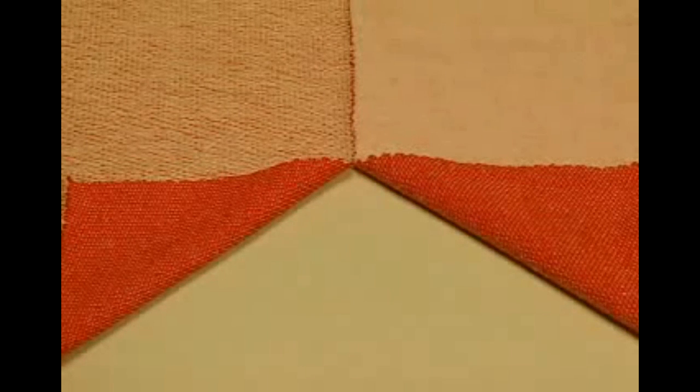This checkerboard pattern uses gray and white yarns. When the gray yarn knits, forming a gray square on the front, the white yarn floats to the back. If you turn the fabric over and inspect the back, the colors appear reversed. A second use is to create surface effects or change the performance of the fabric. You can make loops float on one side of the fabric, then nap them to produce a fleece. If not napped, these floats can be used for aesthetics or function.